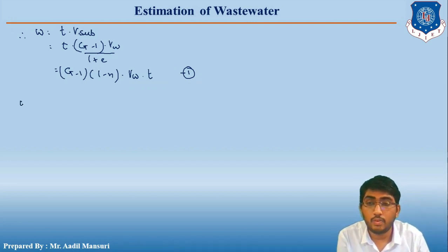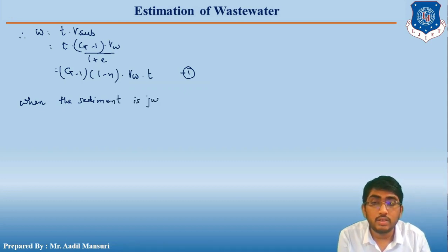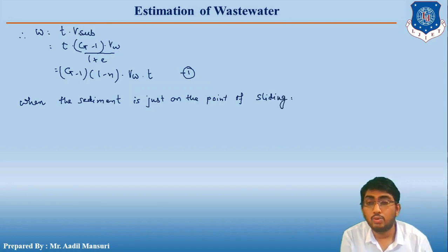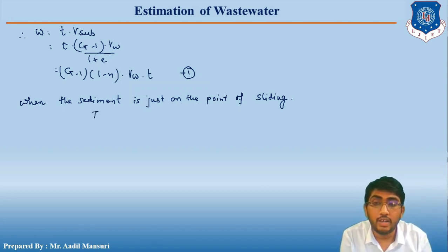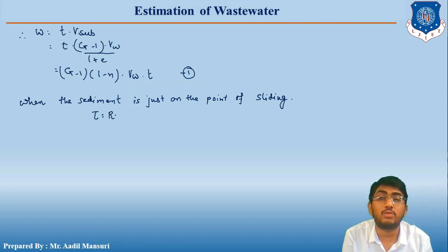Now, when the sediment is just on the point of sliding, that is, when the sediment which is at the bottom of the sewer is just about to slide, at that point of time drag force is always equal to the resisting force. It is from the fundamentals of friction.